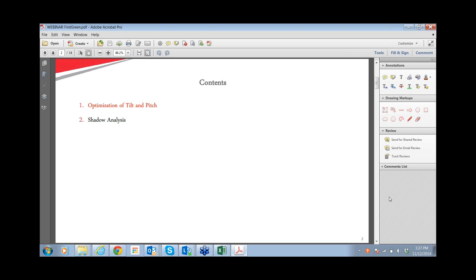Then the other part was landscape and portrait, which Sanjay was talking about. As Sanjay told, there are numerous options of module mounting structure, like two portrait, or four modules, one above the other in landscape. Another parameter which affects module orientation is alignment.